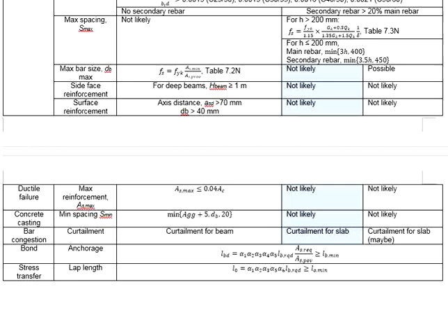Because of the characteristic of the steel reinforcement, after yielding, the reinforcement bar undergoes significant elongation. Such deformations can lead to excessive cracks on the surface of the RC members. This leads to ductile failure of the members, and the cracks on the members can easily be noticed as a warning sign that the member is about to fail. This behavior is very important for survival purposes.